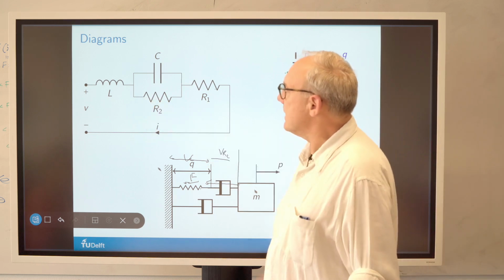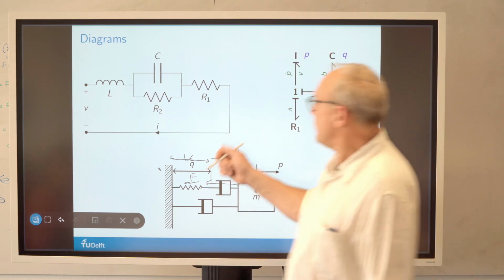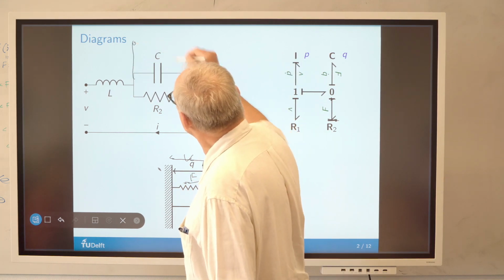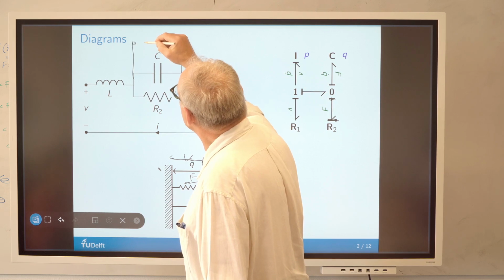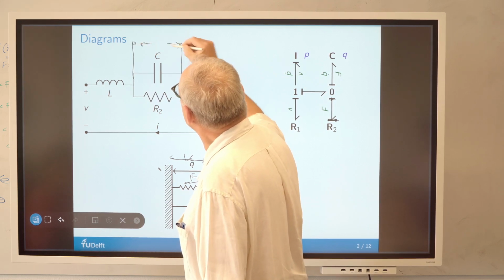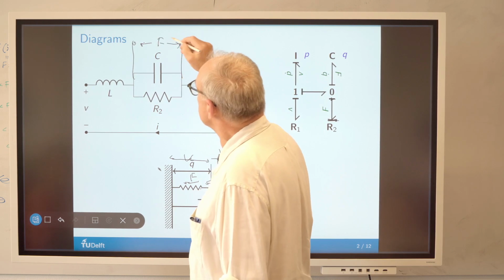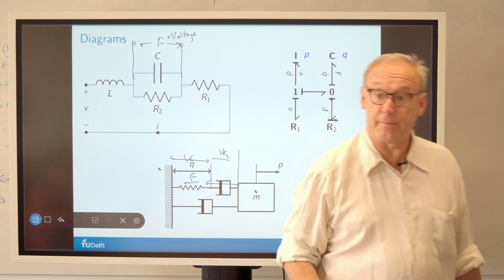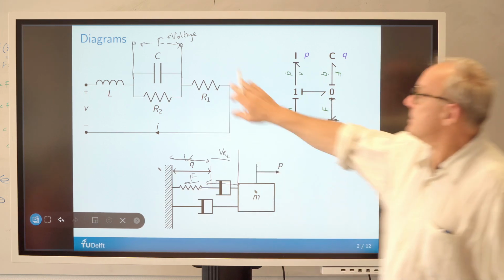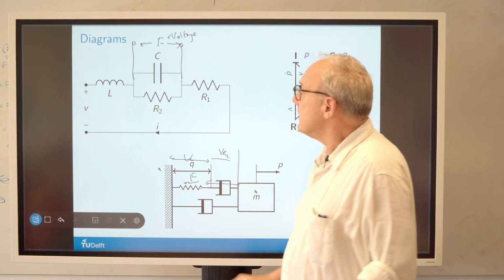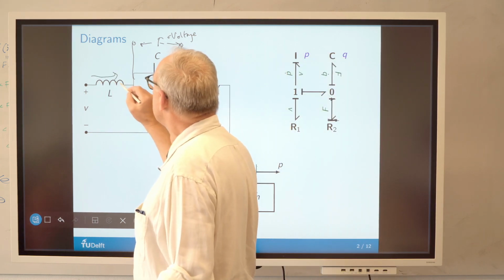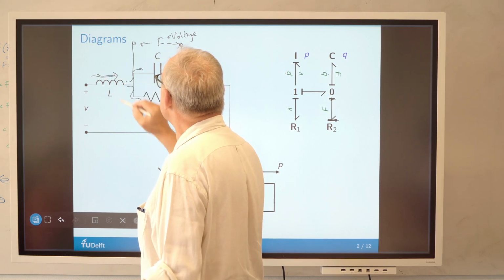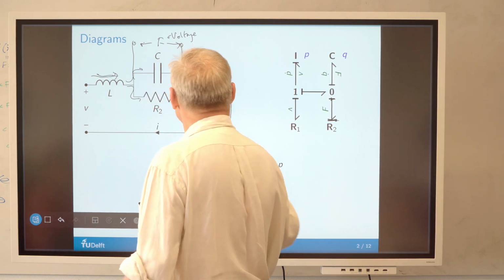Here, the situation is reversed. Where's the force? Well, it's a joint voltage on both the spring and the damper, so it will be over here. This will be the force, which is the voltage, right? The potential drop. So the voltage is measured in a cross way, and the current is measured in a sort of through way. We see this current going here, then splitting in two, and coming together again, and then it's flowing around.